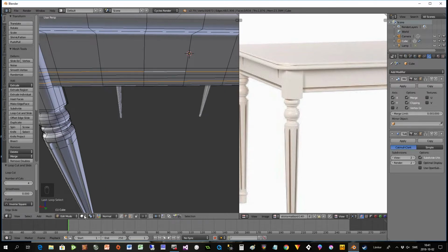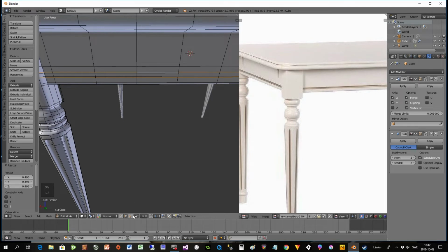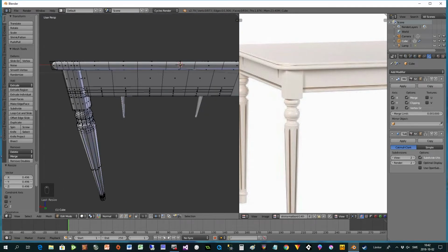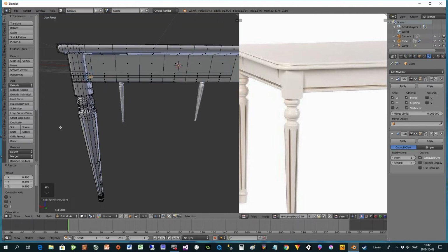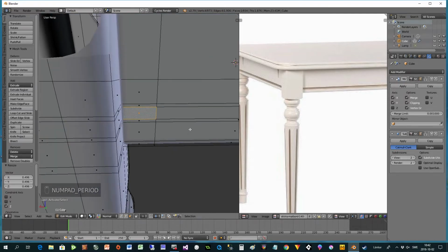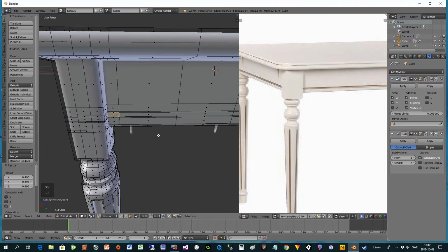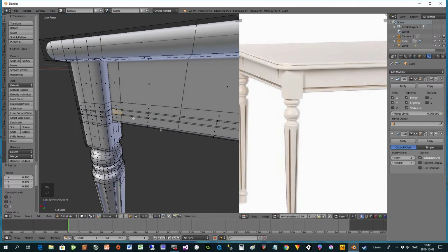and to make the move, you have to change this to median points, because then it takes the median between these two, which means if I press S Z it will go down, and I go almost down to the middle here, but not the complete way, but almost. And then I change to faces here, and I can select, let's see here, so we can take that part here. And if I now take numpad period, I go to the selected here. I used view selected.